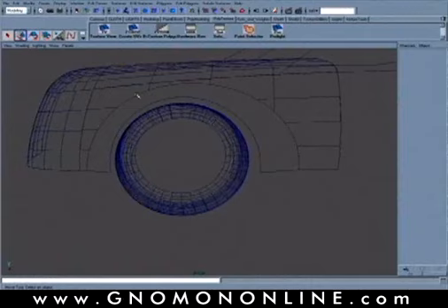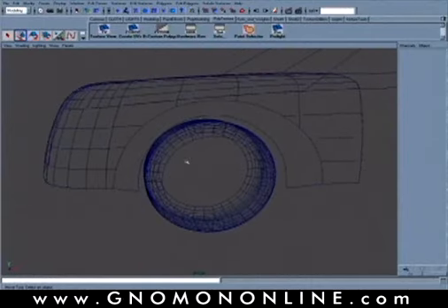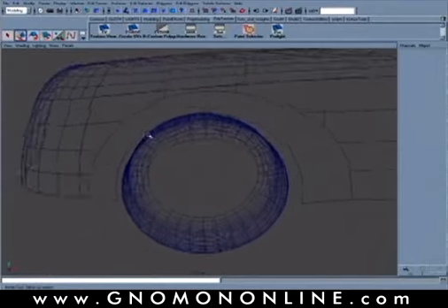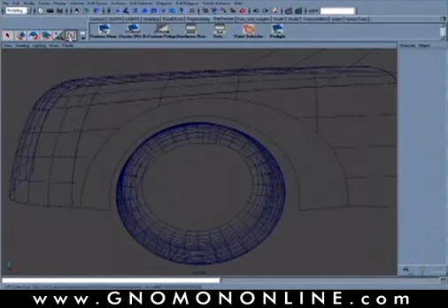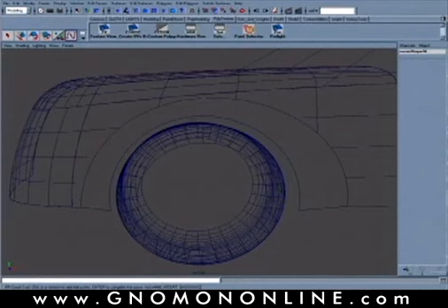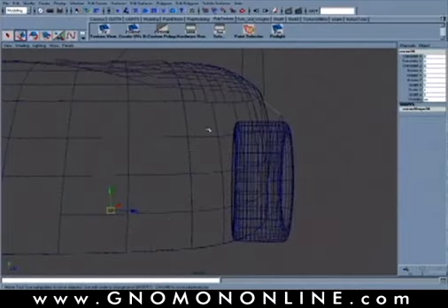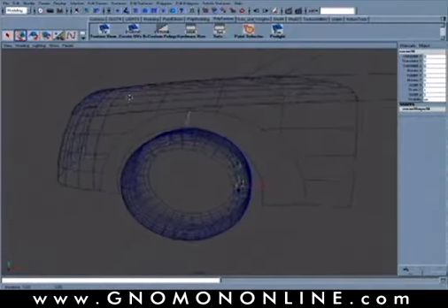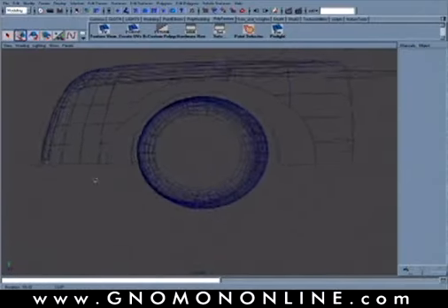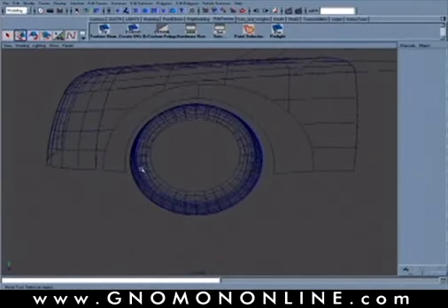We do have 4 boundary curves, but you may want to have a little more control at the top of the arch by adding a third curve that will extend between them. And this is done again with the edit point curve. Curve snap it up towards the top, and then curve snap it onto that extending curve there. So this will start to create that angled away surface and designing basically how that wheel arch is going to be formed here.